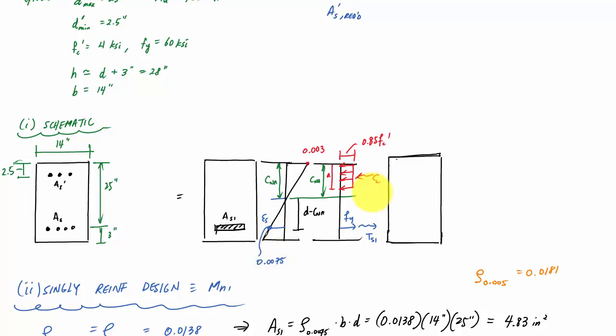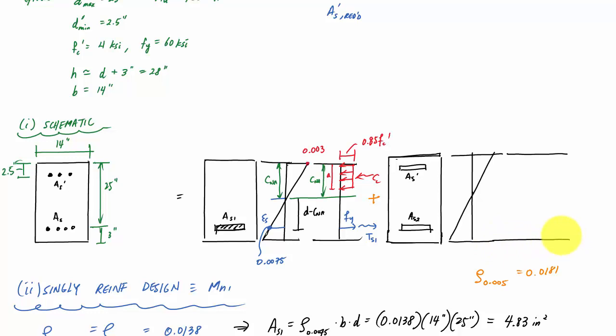So I have to add both tension steel and compression steel to keep that balance, keep that equilibrium, right? And here we need As2, and we need some sort of As prime, right? And the strain profile is the same, so there's no mystery there. That strain profile is the same, and then I have a stress and force profile.